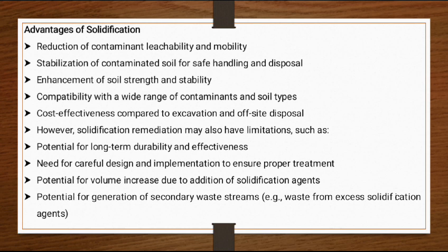However, solidification remediation may also have limitations such as potential for long-term durability and effectiveness concerns, need for careful design and implementation to ensure proper treatment, potential for volume increase due to addition of solidification agents, and next one is potential for generation of secondary waste streams, for example waste from excess solidification agents.